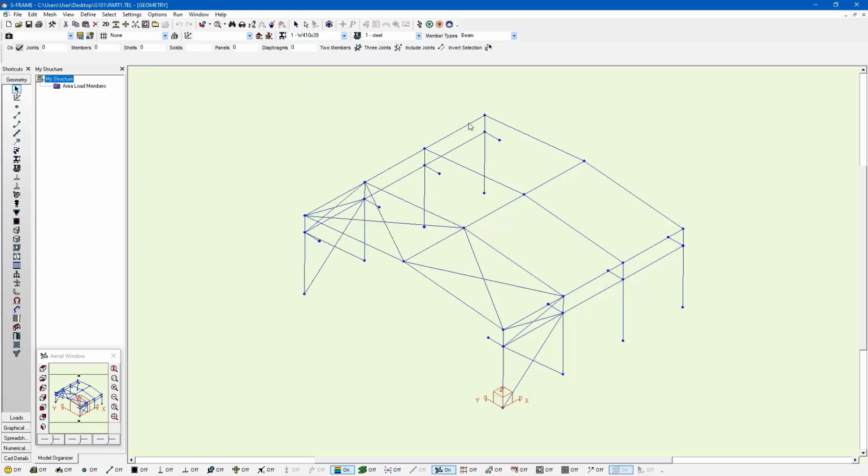And another shortcut key is we can use the shift button to do a line selection rather than a box selection. And using the combination of the control and shift keys at the same time and left clicking and dragging my mouse will unselect those objects along that line.